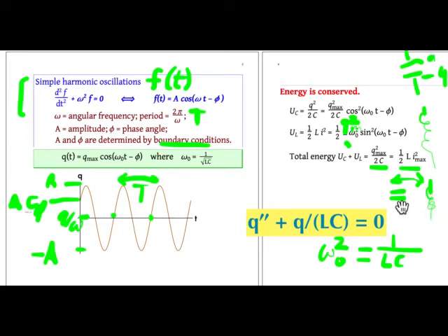And a half cycle later, or a quarter of a cycle later, I guess, the energy is all in the inductor. So we have also alternating fields. We have an alternating electric field and an alternating magnetic field. But the total energy of the two fields is constant. And that's an example of energy conservation. So conservation of energy is a universal principle. And in the LC circuit, it shows up in the fact that the energy of the capacitor plus the energy of the inductor is constant.